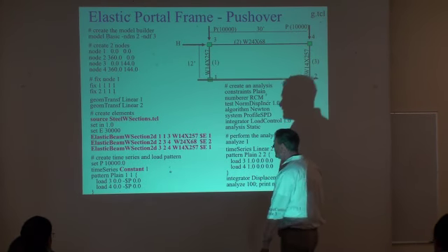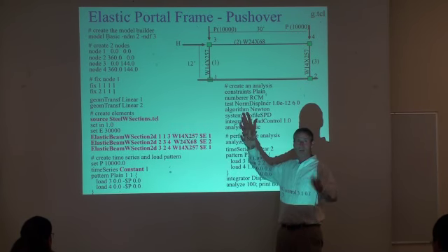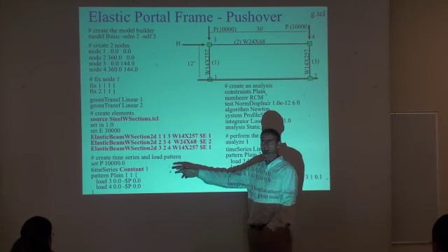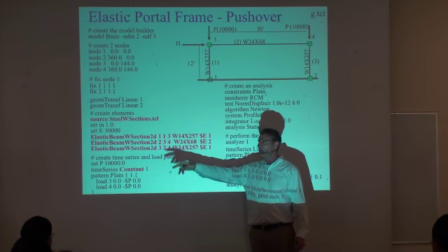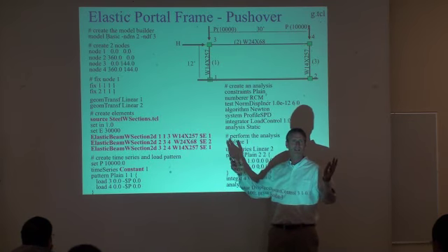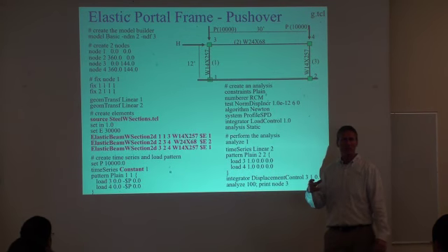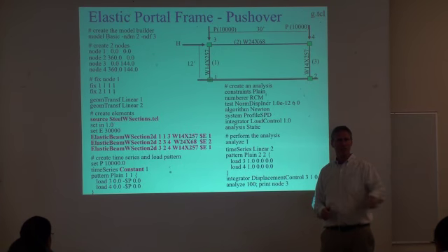OpenSees doesn't care what you've got in your model. It says, oh, I've got a load pattern. Okay, load pattern, here's the time, go apply yourself. So the load pattern asks, what's the time of the domain? Okay, give me the load factor from the time series. Now, all you loads, here's the load factor to apply to the elements or the nodes.